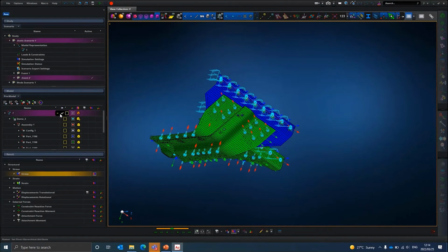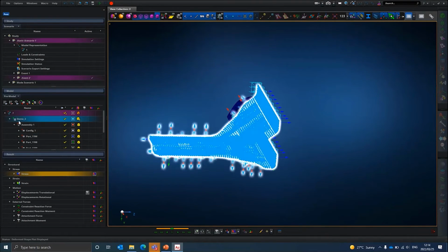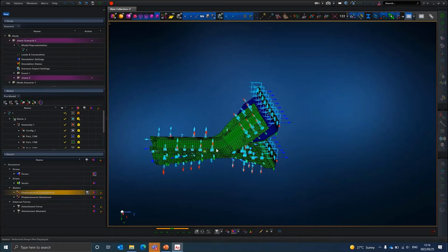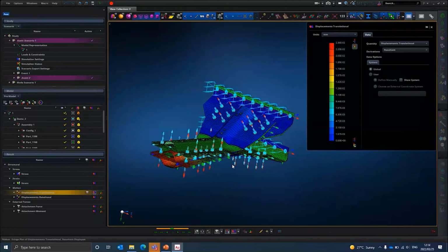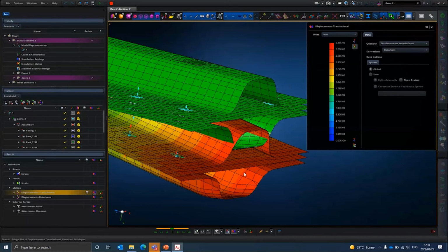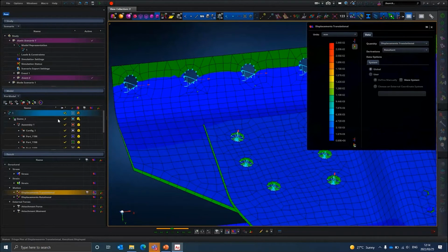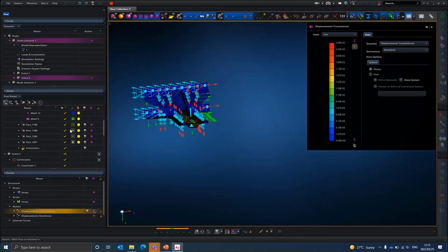Now you can see here everything is switched off, but if I switch it on and I just put my displacement deformation back on and I select my whole model and just quickly plot my deformation again, I can see now that just plot the fringe as well, then it should make it easier to distinguish. So here is my deflected or deformed model, and you can see there is my original model as well. If I want to go back again, so that I do not see my undeformed model, I simply just switch it off and I go back to my post model.